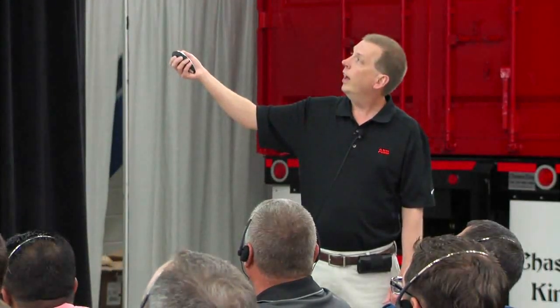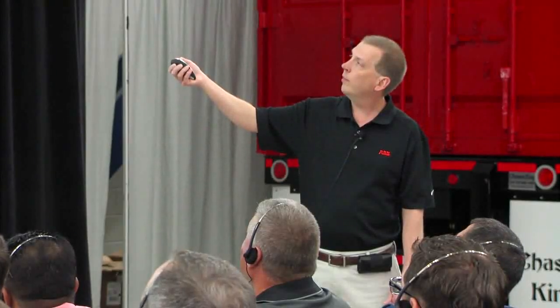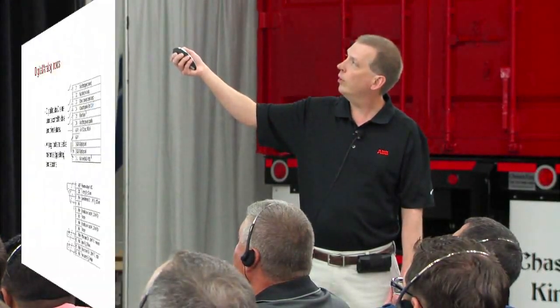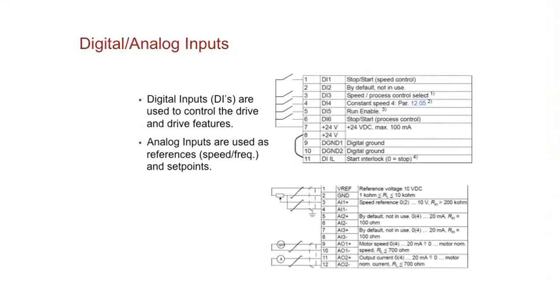Well, I have here, this one happens to be run off a potentiometer. So I have a 10-volt reference level here on pin 1, and I have a ground on pin 2, and I run those into the pins 1 and 3 on the potentiometer. And then I run the middle, the wiper arm, into the analog input. So this analog input now can vary between ground, or 0 volts, and the reference of 10 volts.